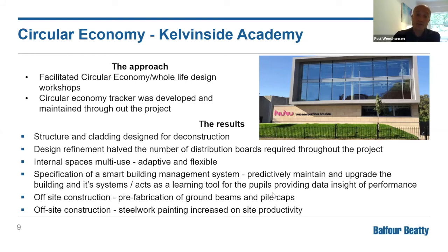And then off-site construction, steel painting, that's another factory that we have. It is just one element, but we can do modular M&E installations, and as we've heard, get that quality control off-site, which reduces reworking and potential issues with quality on-site, and gets things done quicker to a more guaranteed standard.